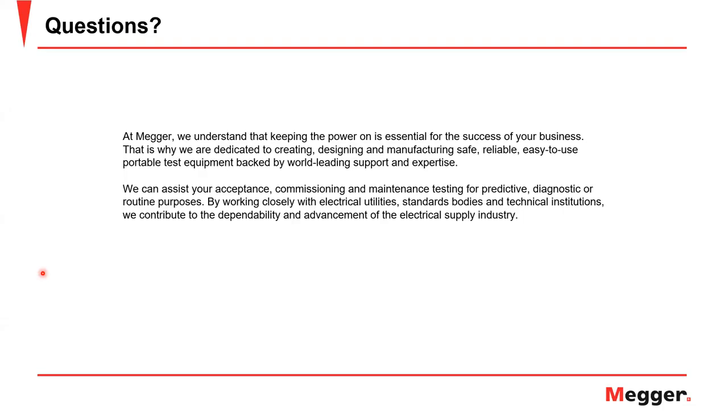Is it better to make the CB trip before the fuse due to the time spent replacing the fuse? It could be. It all depends on the utility practices, as Mike was explaining in his presentation. Various utilities adopt the philosophy of a fuse saving scheme, whereas some adopt a fuse blowing scheme. In the fuse blowing scheme, the fuses are gone, and you have to send manpower out in the field to replace them, so there is a manpower cost and an outage cost.